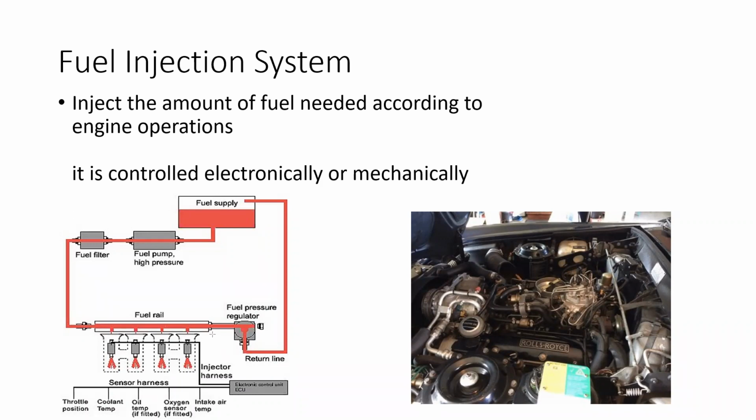So it's a common rail of fuel, right? It's sort of like a cylinder arrangement which is filled with fuel. To this fuel rail, if it is a 4-cylinder engine, each cylinder has a different injector. These are electronic injectors which are actuated only with an electric signal, right? These can be switched off and switched on based on an electric signal.